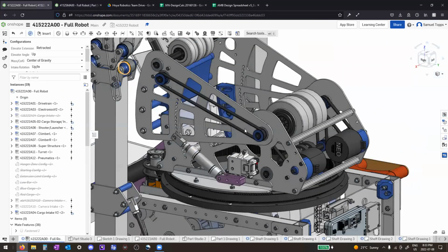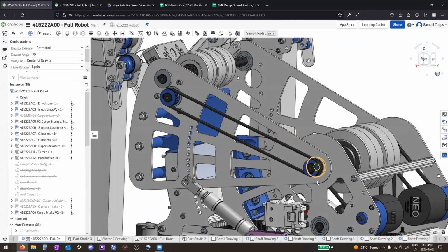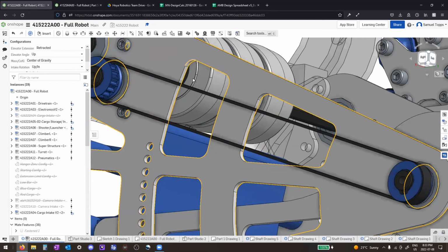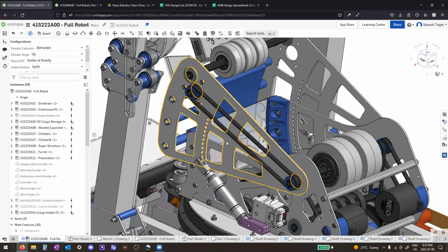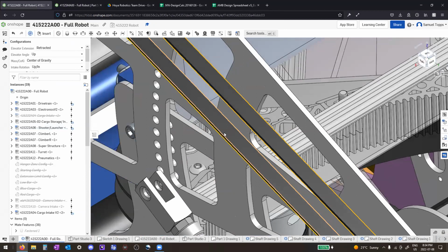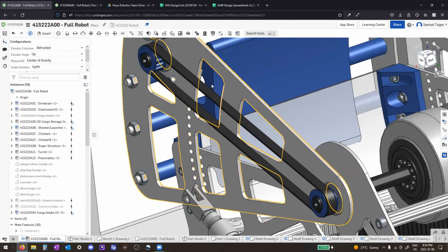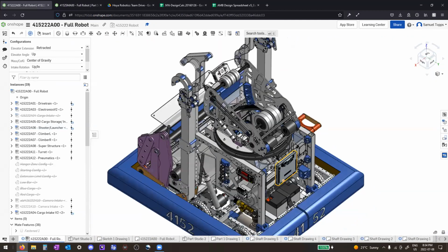So if you look at our robot, all our corners, some of it may be excessive or whatever, but every little corner has rounded corners in it because it's easier for cutting and it reduces the amount of stress on the part without really adding much weight. So that's just something to consider when you're making all these parts. Same goes for 3D printed parts.